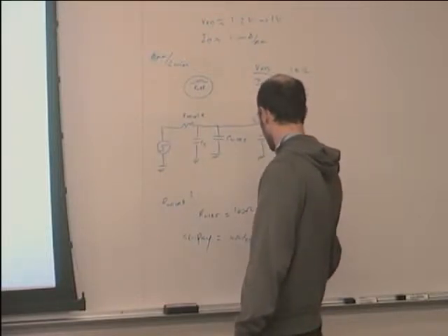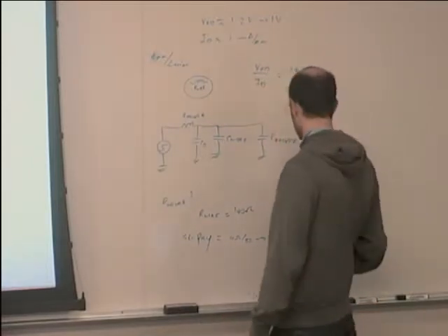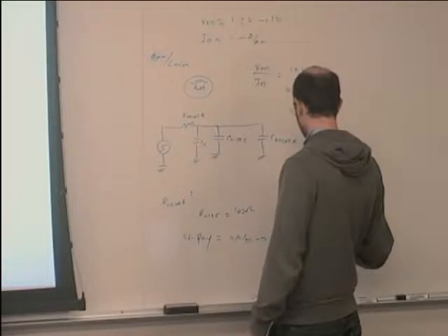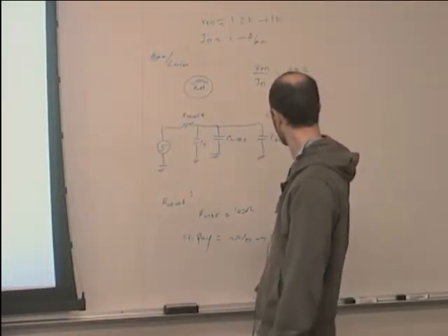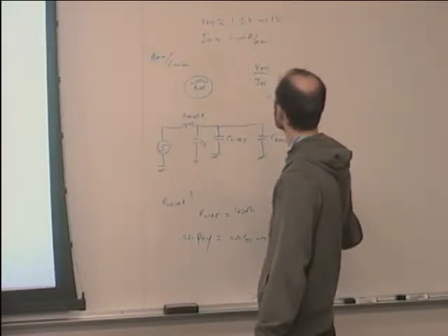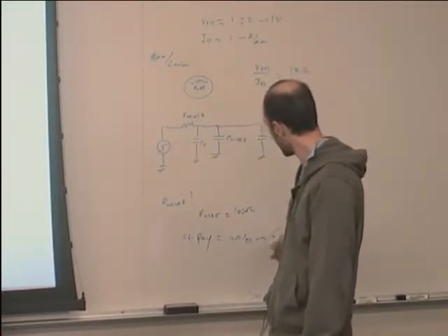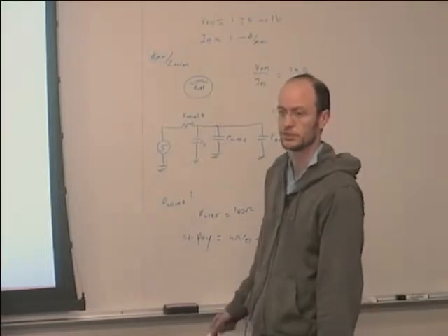So to make it 100 ohms, you need 25 squares. If you are in 65 nanometer and the poly is minimum width, this means 1.5 microns. After 1.5 microns of routing length, you've already picked up all this resistance, 100 ohms.